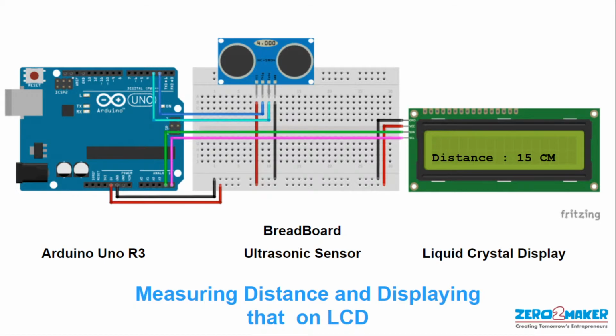Now we have one more output component which is called a display. This is basically an I2C display. It also gets some command from Arduino, which is basically the distance recorded by the ultrasonic sensor. So there will be a logic stored in Arduino which takes the input from the ultrasonic sensor, calculates it, and displays the outcome on the LCD. So this is the second mini project which you can practice once you have the proper components with you.